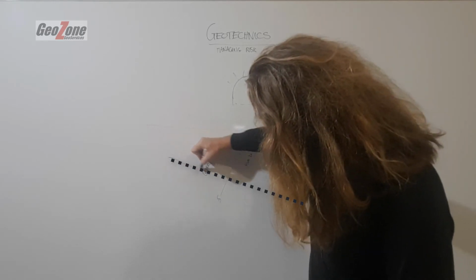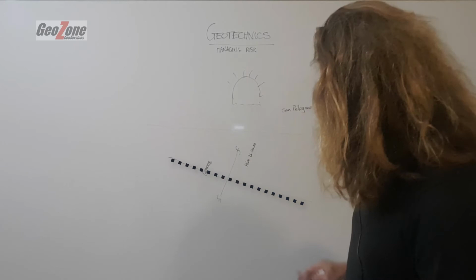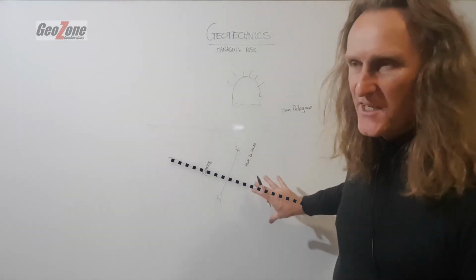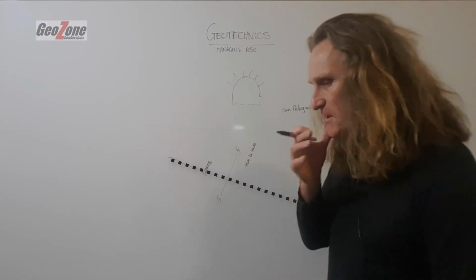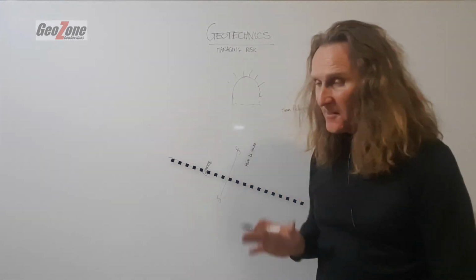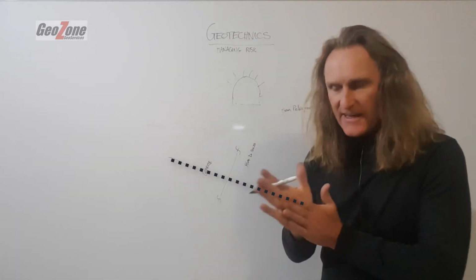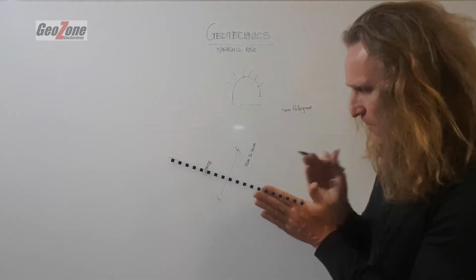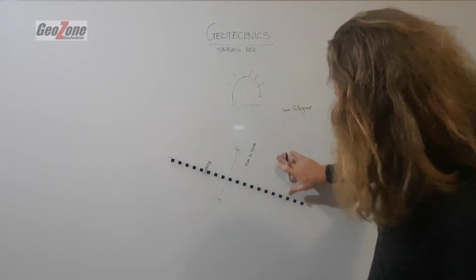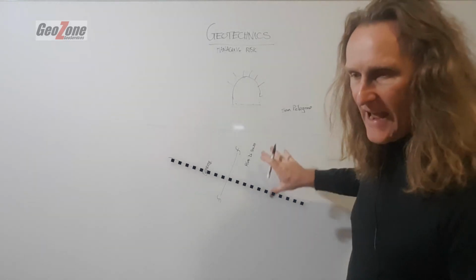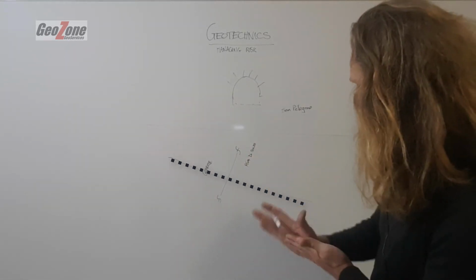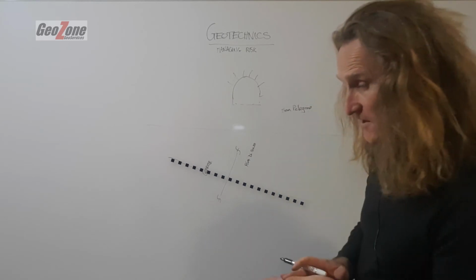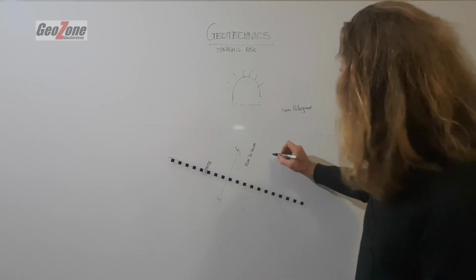They're driving a tunnel this way. This was awful, squeezing black shales. I remember bringing some samples home to test. It was on my master's project. The stuff was like polished glass. The discontinuities were smooth, as smooth as this board, and black, polished. It was like obsidian that had been saw cut. Beautiful, beautiful, beautiful surfaces. Shear strengths of 12 degrees,